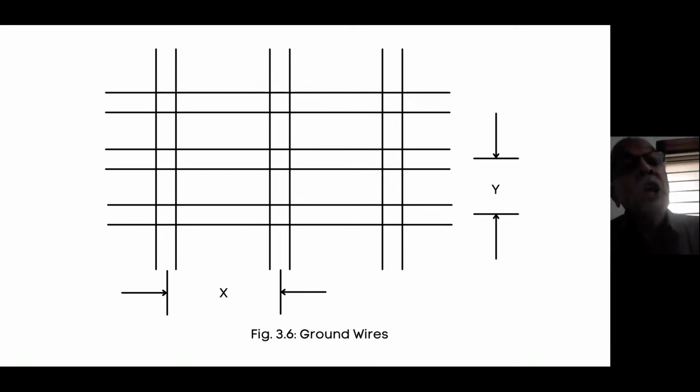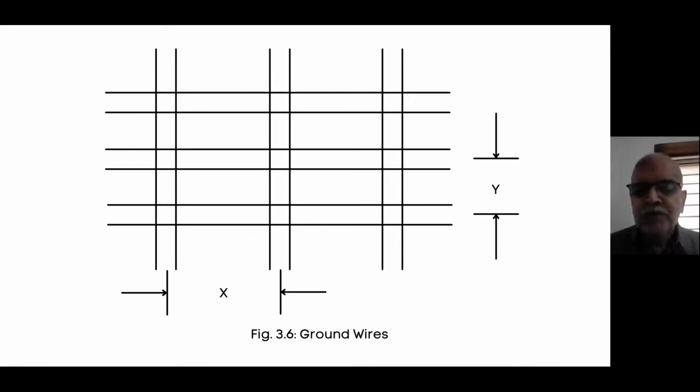And your top ground wire has to be connected to either ground rods, ground wires, or to the counterpoise wires. So this makes the top ground wire non-stop, continuously throughout the length of the line, with ground rods or counterpoise wires, and shielding angle.